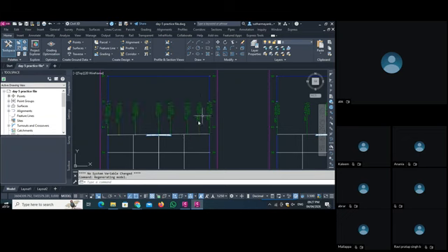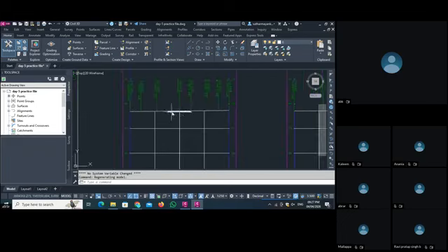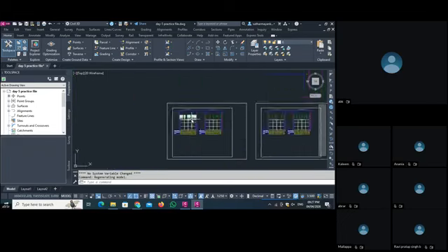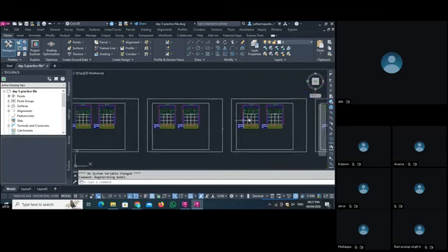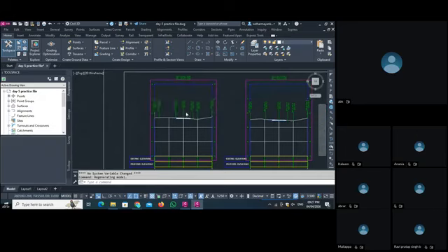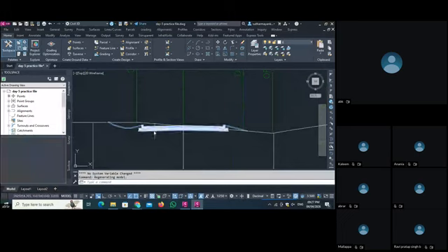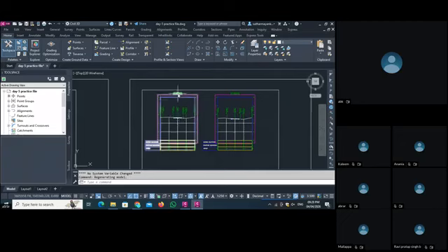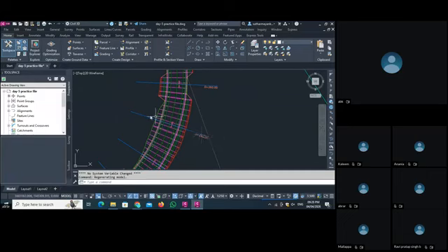Now, this is our cross section. You see here, our corridor. You check our corridor properly. See, let's check it here on a 40-meter of chainage. See, you can check all the station chainage. See here on a 280-meter, our sample line on 280-meter. See here our sample line on 280 meters. So I am checking this sample line.